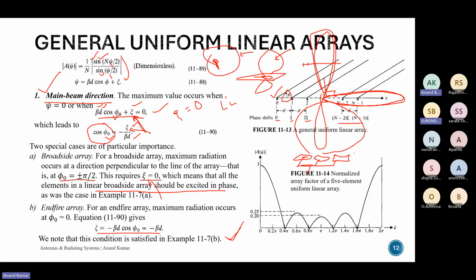Yes. And you want it to be an end fire. So in this case also, I think this math should work. If we make the phase shift equal to minus beta d, this should work. Or otherwise, start with this, and then we can start tuning the phase shift value among the different elements. For an end fire array, there has to be a progressive phase shift, and how much that phase shift would be, you can get an approximation from here, the end fire array, and then you can tune that phase shift between the different elements.